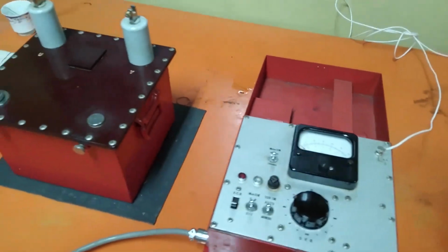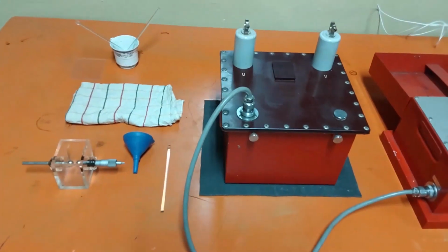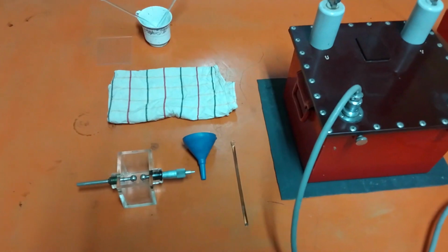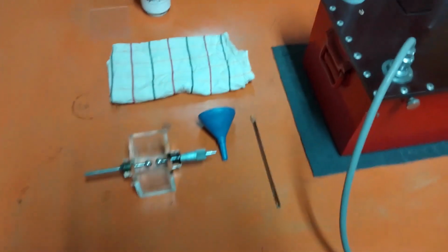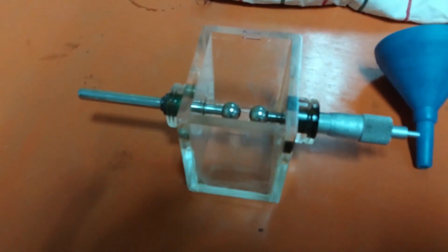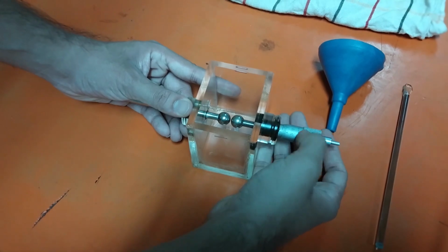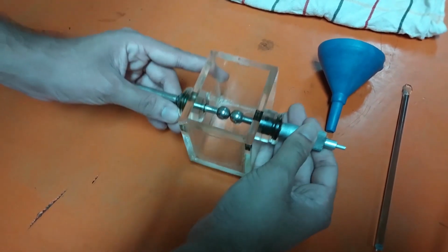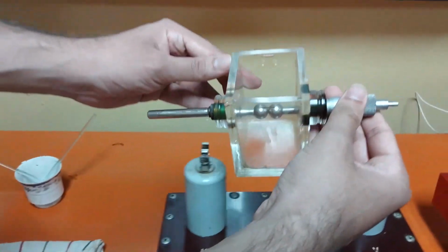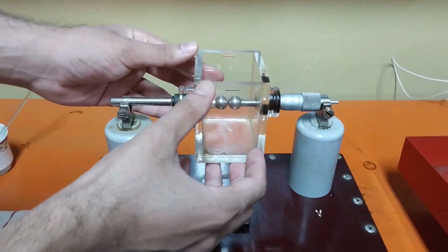And then we have our high voltage terminals, right, U and V, which are represented on top of the terminal box, and this is our glass container with two spherical electrodes. Then we have to adjust the initial gap setting of the two electrodes to 0 using the micrometer screw gauge, as you have just before seen, and then we can safely fix it to the upper middle part of the high voltage terminals like this.